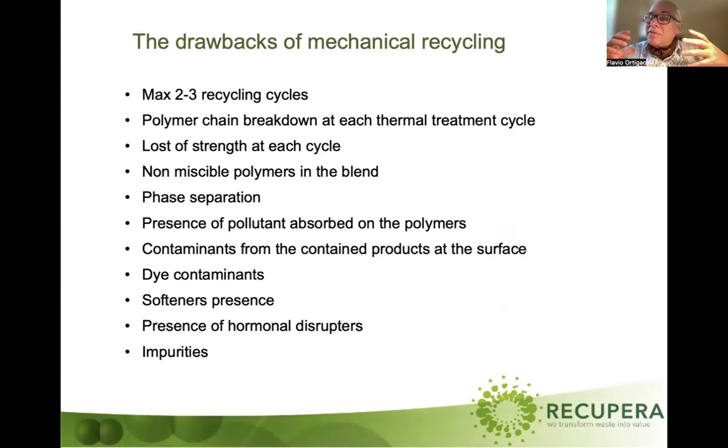You have the polymer. Every time you process the polymer, the molecules will break, and by breaking, it will lose its physical characteristics and not perform as it was intended. That is why you cannot really call it recycling. You are downcycling the material. After two or three rounds of recycling, the material is no longer usable, and then you go to incineration or landfill. There are many more problems with mechanical recycling. So the idea that you can recycle polymers by mechanical recycling is not really working, and has never really worked. It is very, very limited.